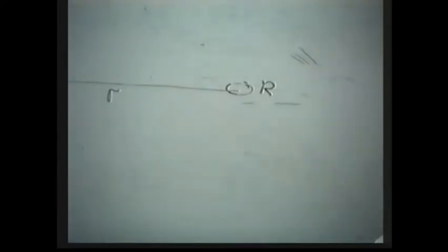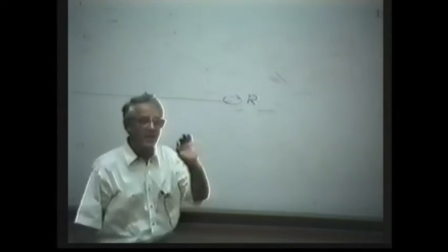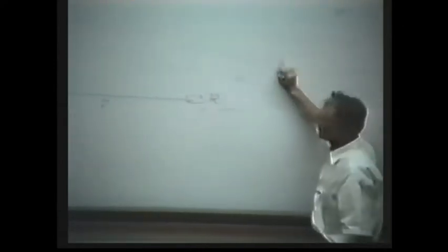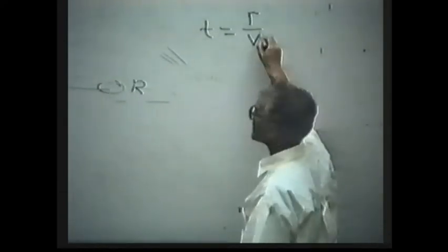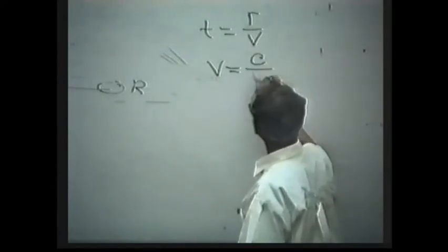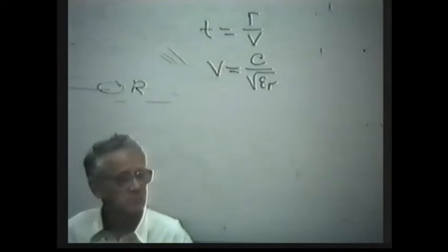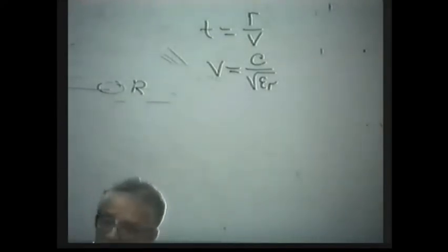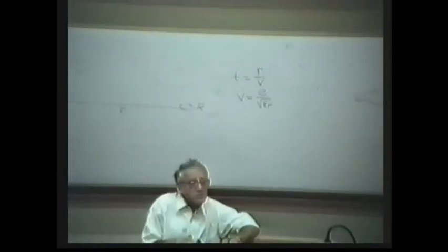Regardless of the conductivity, it arrives at a moment equal to distance divided by velocity, and the velocity is the velocity of light divided by the square root of the relative dielectric constant. For instance, this method is used in dielectric logging in order to measure the dielectric constant.